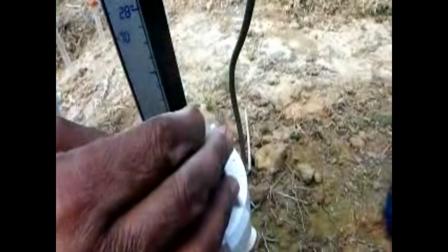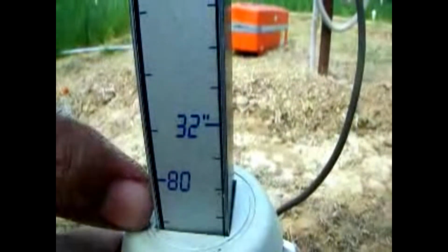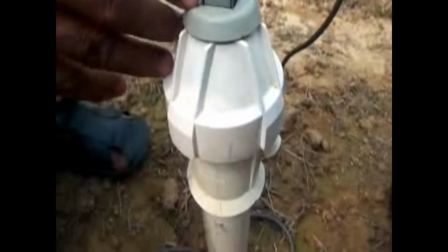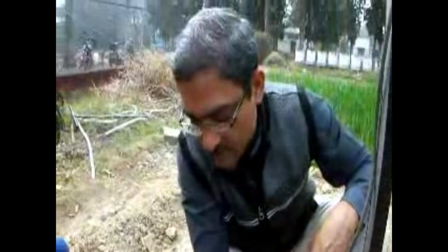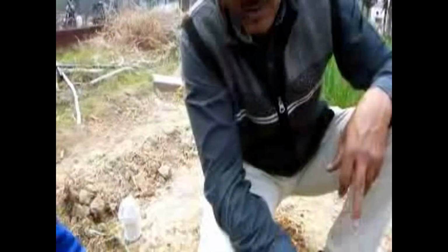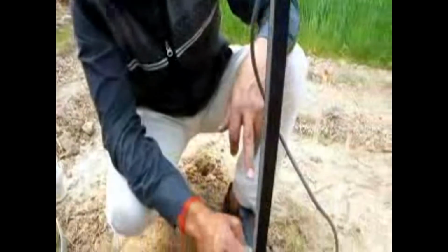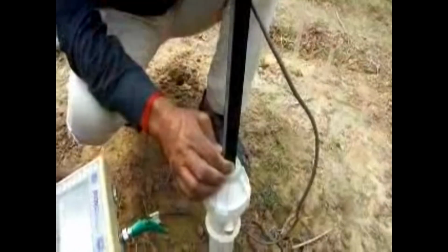Now let us go to 60 centimeter. So 60 plus 19, 79. It is going to 79 centimeter depth, and here we can find out what is the soil moisture. This is giving 35.1 percentage. So now in this way we have soil moisture for 30, 45 and 60 centimeter depth of soil by using FDR method. It is in percentage.